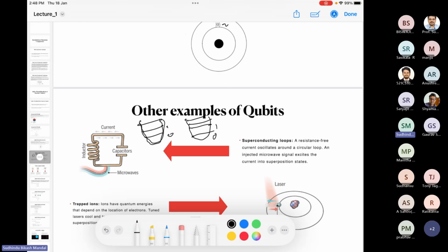So we need to separate them. Within the refrigerator we put our qubit or anharmonic oscillator, and the pulse toolbox is completely outside the refrigerator. We need a big cable to transfer this signal. Within this cable, when we send these microwave pulses, they interact with the environment. So it is very difficult to send an accurate pulse, and that's why noise comes in.